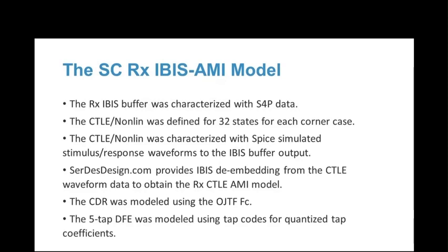Thus, the combined IBIS buffer and AMI model provided the same characteristics as defined by the receiver stimulus response waveform data. The SerDesDesign.com channel simulator automatically did that de-embedding. The CDR in the receive circuit was modeled using the observed time jitter transfer function corner frequency to estimate for the circuit CDR, and the DFE in the receive circuit was modeled using 5 taps, with each tap defined with a set of states quantized with a set of tap codes.